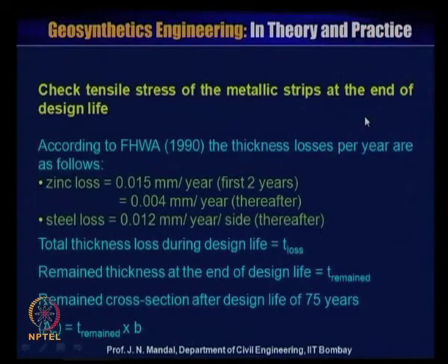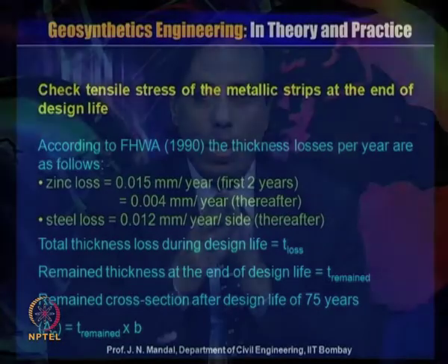Because we are using metallic strip reinforcement, we should also study the effect of moisture, the corrosion effect of the reinforcing material, and the longevity and durability of this material.